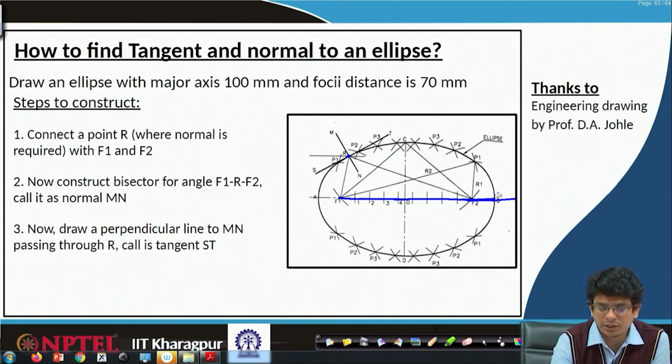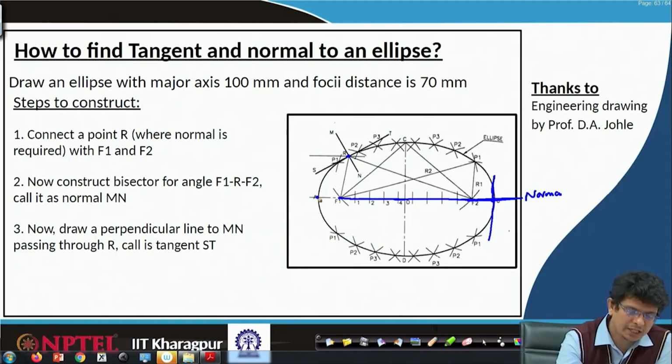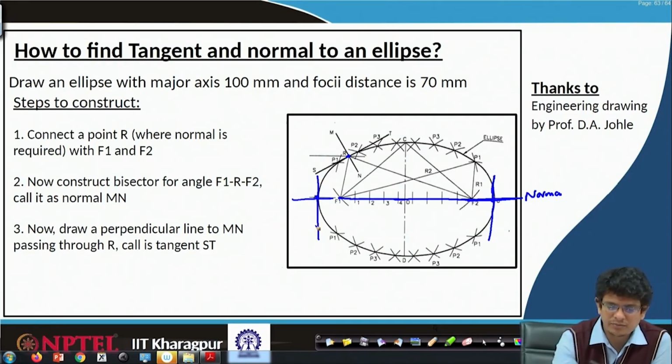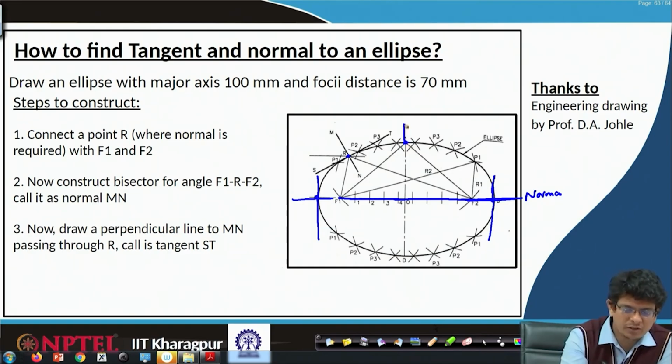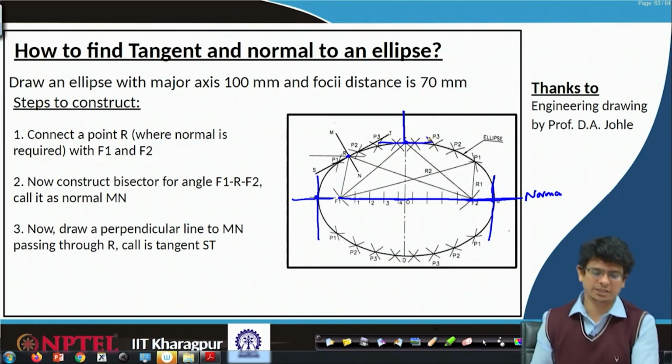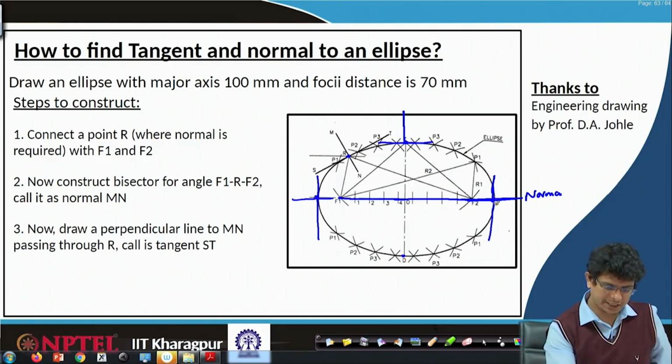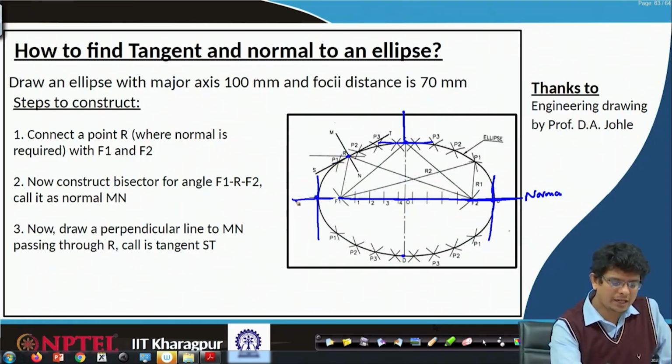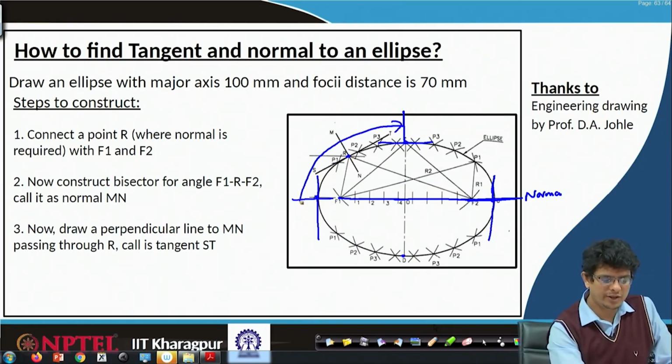line. So, this is the one which makes the normal to that curve at this point, and the tangent will be perpendicular to that. The same thing happens here, normal will be in that direction, tangent will be in that direction. If we pick point C, normal will be in that direction, tangent will be in the other direction. Except these 4 points A, B, C, D, at the remaining points, this normal angle continuously increases as you go in that direction, all the way from 0 angle to 90 degrees.